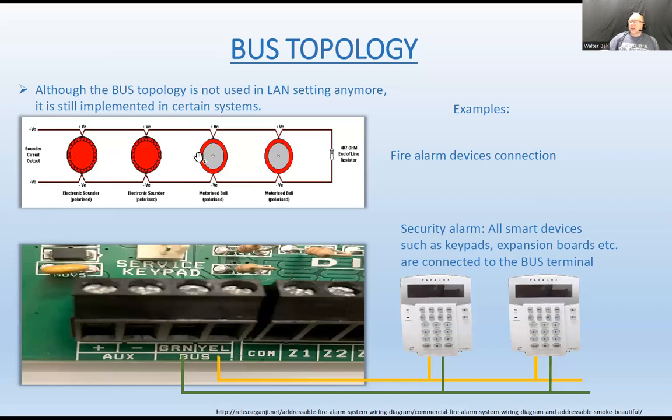Those devices are normally open. So under normal conditions, when nothing happens, the zone doesn't even see any of those because they are connected as normally open devices. They have a bunch of circuitry that is designed to sense certain types of conditions, for example, smoke present, heat present, and whatnot. But on the output of it, there is just a dry contact. And when it's idling, that dry contact is open. So this zone is not even seeing those.